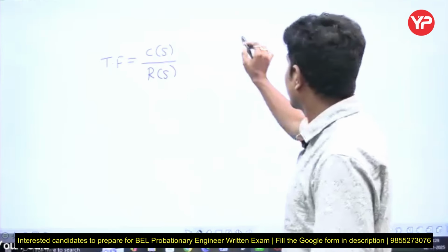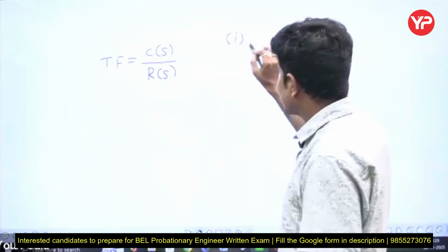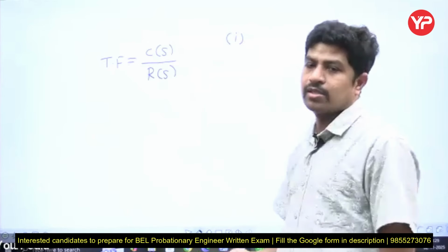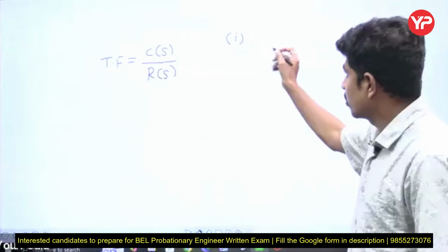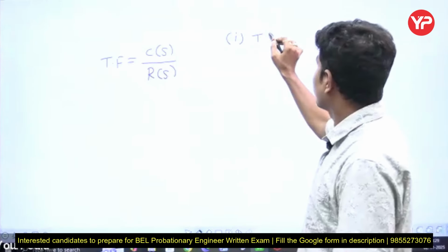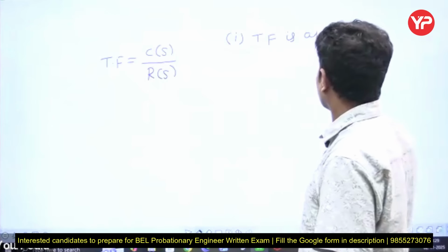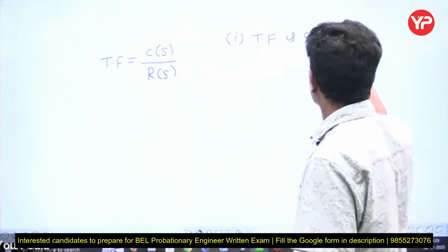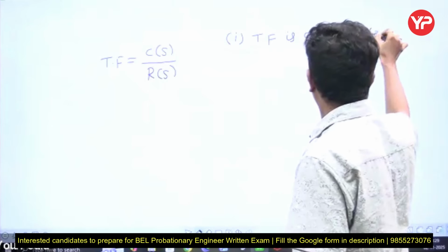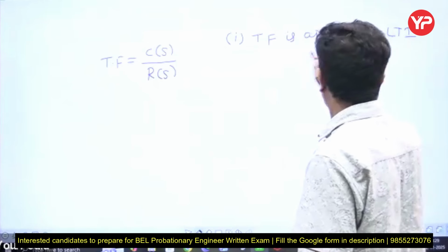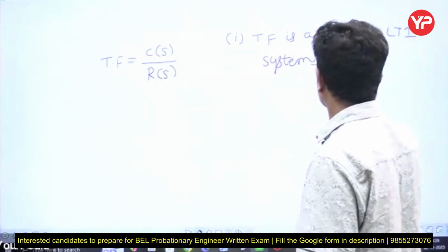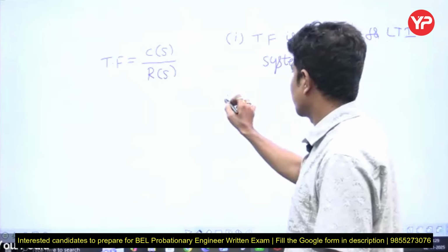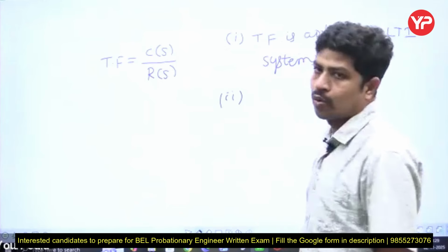The very first point related to transfer function is, the system must have zero initial conditions, meaning there should not be any previous energy in the system, then only you can apply transfer function. First of all, transfer function is applicable for LTI systems, linear time invariant systems only.